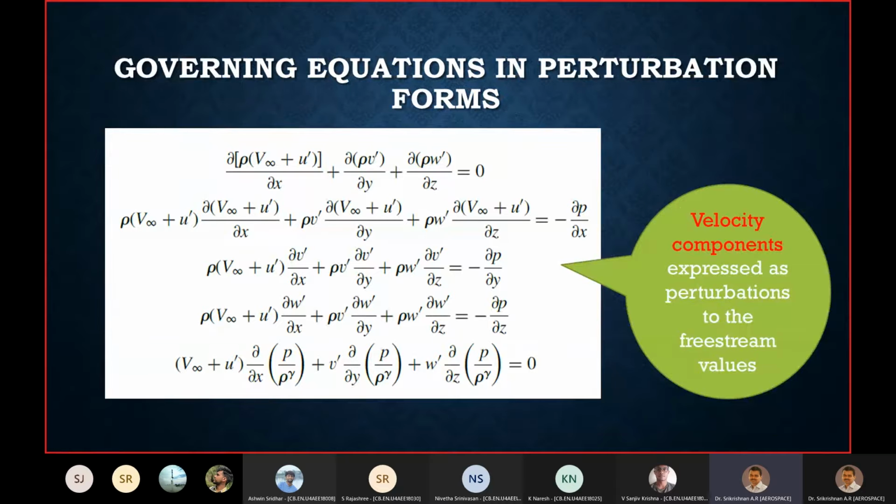That is, we consider the velocity field to be perturbed, that is disturbed a little bit by the presence of the body. The disturbance is small in relation to the mainstream velocity. And because of that, we can neglect some of the terms that would eventually manifest in the relation. Based on that, we can restate the governing equations by adding the velocity components u dash and v dash to the x and y components of the velocity.